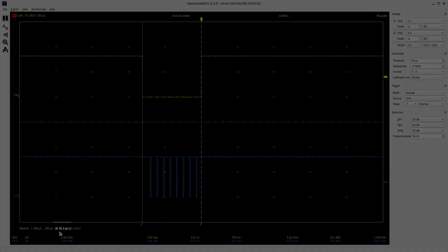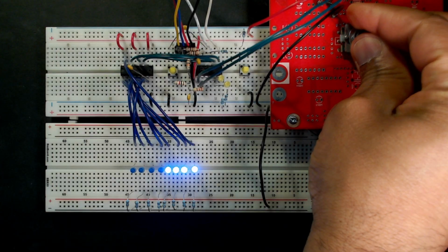This thing takes just over 80 microseconds to process. And that's based on our current microcontroller speed of about 4 megahertz. It is incredibly quick, which is why this is so incredibly responsive. But remember, in our code, we are manually flipping those bits up and down. And when we got started on today's episode, I did say that we're going to explore a peripheral that can do this for us. So let's leverage it.